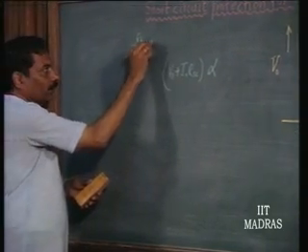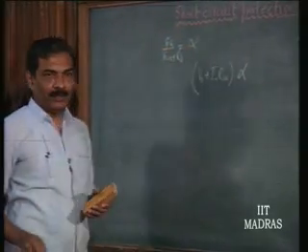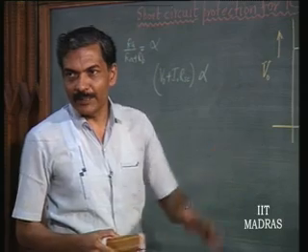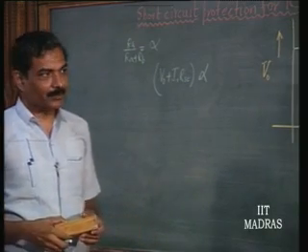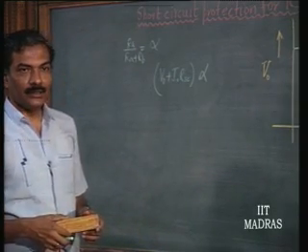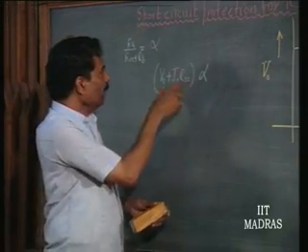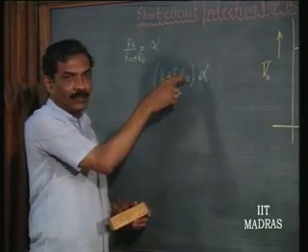Yeah, RA and RB should be large. Just as we select R1 and R2, we are also taking care not to take away too much current from the load. Alpha is nothing but RA by RA plus RB.